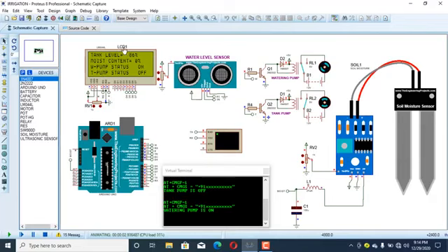now as we see here in the LCD, the tank level is 86%, which is more than 65%, so the tank pump will be off. As you see here, the tank pump is off because the tank level is 86%, but the moisture content is 63%, and inside the condition we say that if the moisture content is below 85%, the watering pump has to be on. So now you see here the watering pump is on, right?